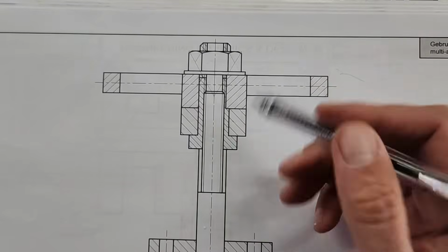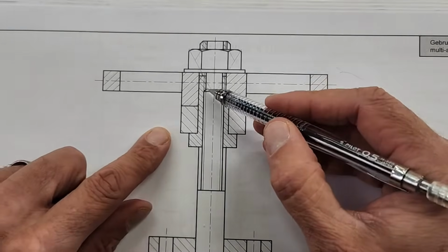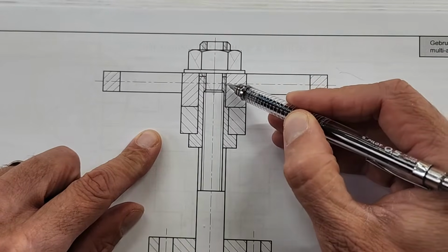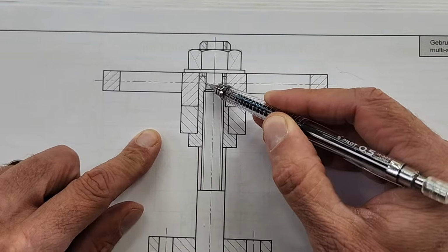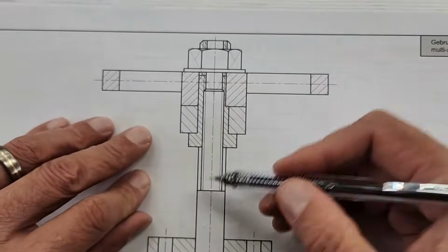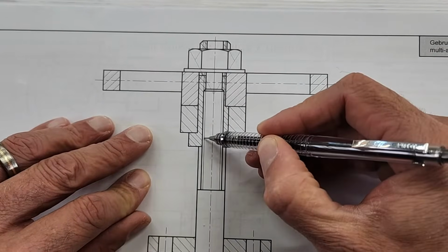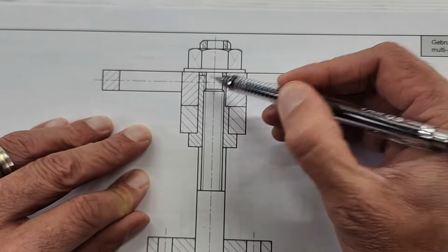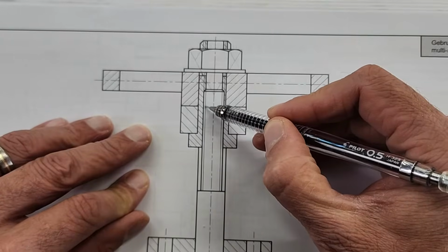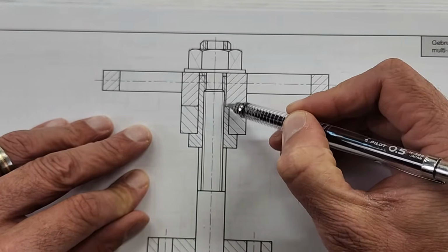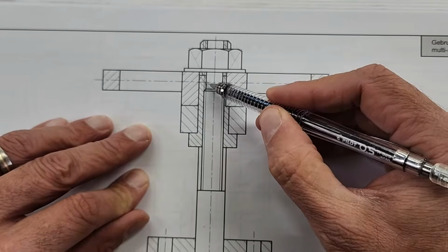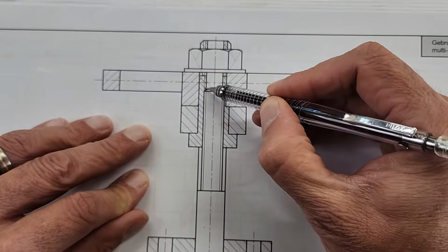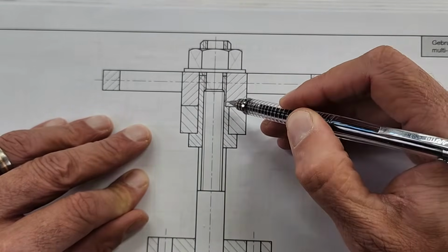Then something else that's important, if we have an internal screw thread and we cut through it, then that section lines need to go all the way to the end if it is empty and there's not something screwed into it. But in this instance, we had a shaft with an external screw thread being screwed into this holder that's got an internal screw thread, and so that hatching does not form part of the screw thread part here. So just take a note of that. But at that part again where it's really air, that hatching continues to the end. The moment that it's joined together, that falls off.